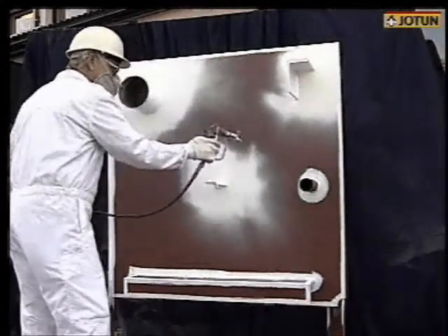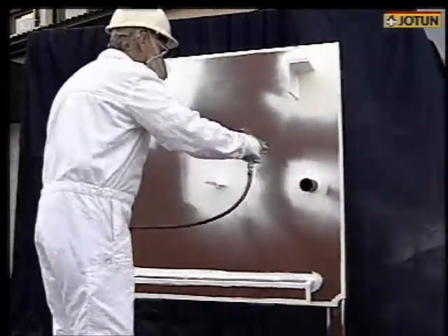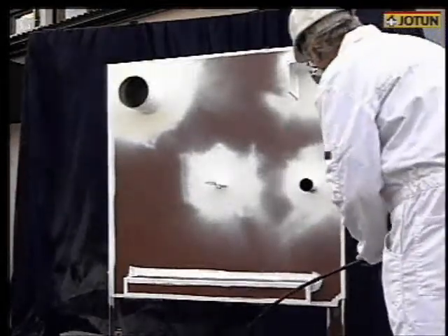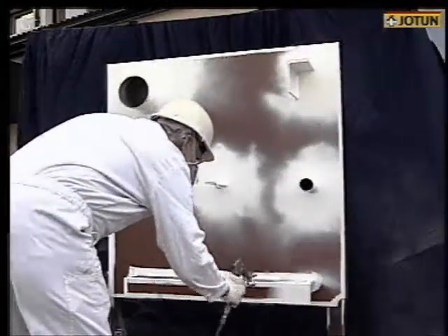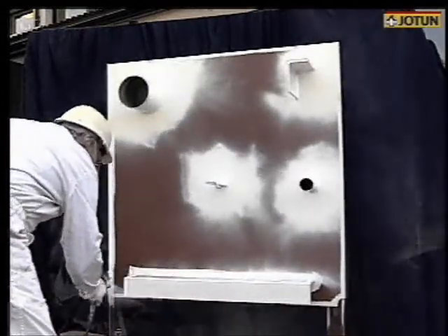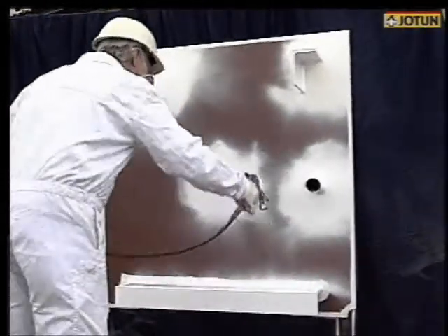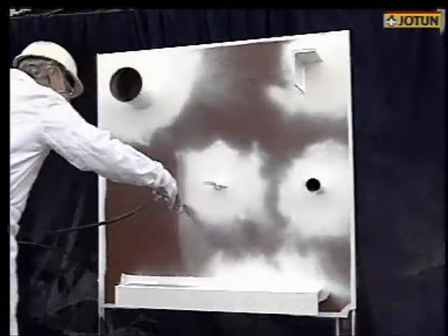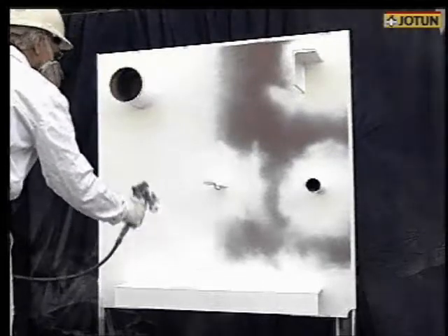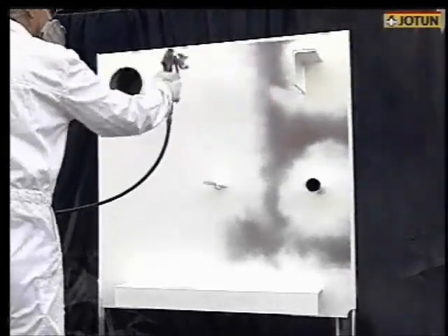Always start with the complex parts. This ensures that the specified film thickness, not too little, not too much, is obtained all over, giving a nice even finish. If carried out in the reverse order, over-application or dry spraying may occur on the large plane areas. In strong winds, the paint should be applied in the same direction as the wind to avoid dry spraying.